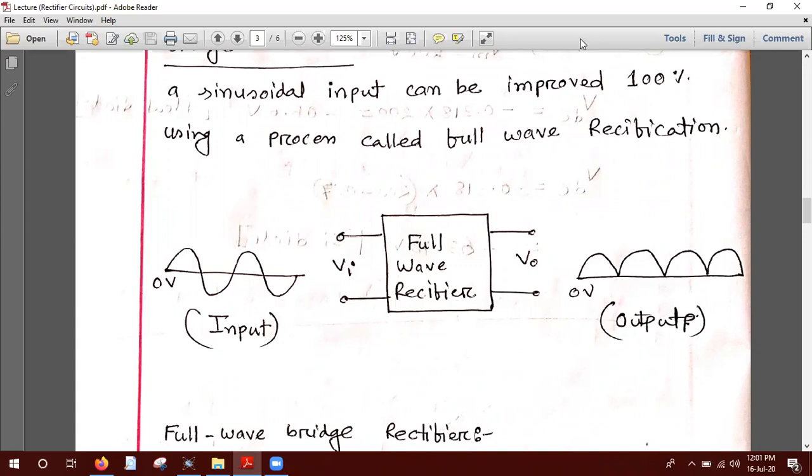The output will look like this. This is the output signal. You see that this is for the positive cycle, this is for the negative cycle, this is for the positive cycle, this is for the negative cycle. But in the half-wave rectifier, this will be for the positive cycle, and for the negative cycle there will be no voltage. Then it will be the positive cycle. So something like that. Today we will see this output graph in the simulation software, because we could not apply it in hardware, but both are the same. At least we understand how they work and what equipment is basically needed for that.